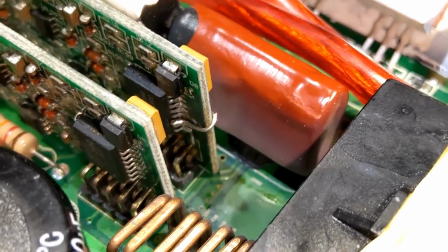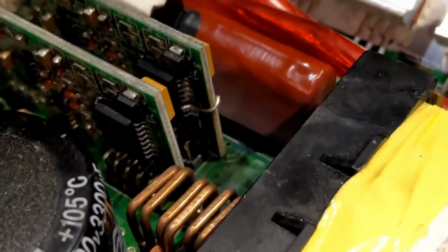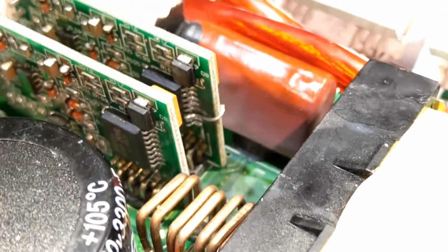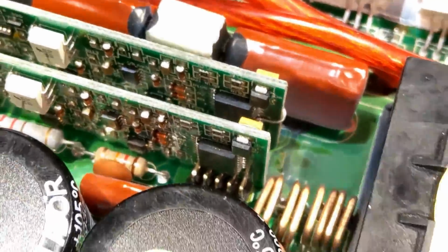You can see there I've had to actually solder to leg 3 to go around the back, which is for VS high side source. So yeah, that was a bit of a mission. The bootstrap diode, I had to replace that one at the top there as well, just up here. I think that was it for this driver card.